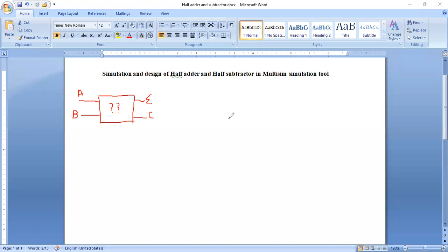So we have two inputs A and B. In that case, we have four combinations. I'm going to design the third step, that is the truth table design. We must have at least four columns, because two columns are for input. So I'm going to mark over here A, second is B, and I'm going to write down here sum, and over here the output function is carry.